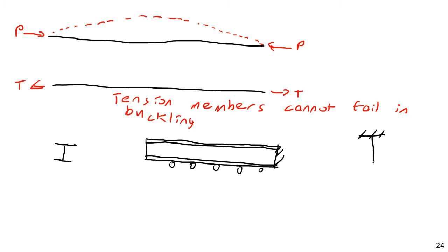I'd see a long, long beam. And let's say this is thousands of feet long. I make a beam for some reason, even a W8 or something. A W8 would be a good example. It's not going to collapse because I have roller support. Maybe, let's say I have roller supports every 2 feet or something like that. A real crazy device. You would build this only for the sake of proving that this is possible. And so this thing is supported vertically, so it's not going to bend down and droop down. But it effectively has no resistance to lateral movement.